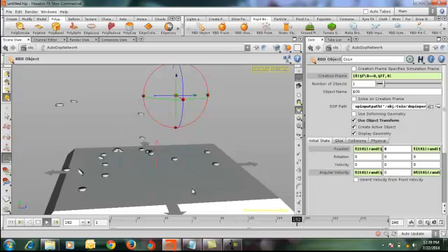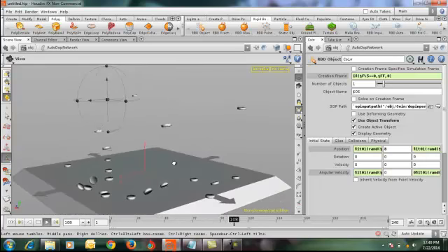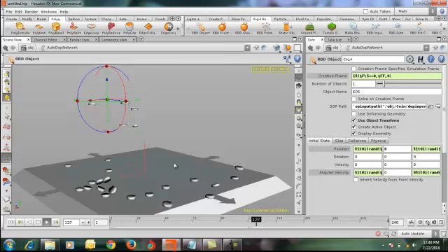See, again, you can randomize this as much as you want. You can keep changing. If you want more coins, change this to 5 or something, so the number of coins is more. So this is how, using our basic expressions, we were able to generate as many rigid bodies as we wanted onto a ground plane. This is a small introduction to how our rigid bodies work in Houdini. That would be all for this lesson. Would appreciate feedback from your end.